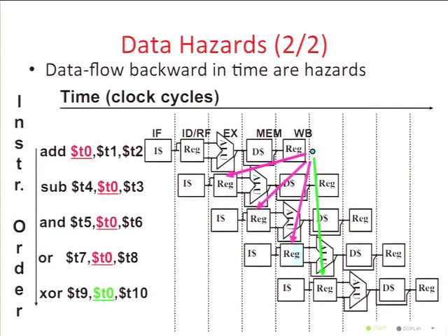So it turns out, where do we know we're adding, we're going to skip that step. So it turns out that right here, we actually know the result of the add, okay? So for the cost of one wire, I could probably solve my problem, okay, or maybe multiple wires. Okay, so this is called forwarding. So I can actually change my wiring in order to solve these kinds of hazards. You got to get the control to work properly then, but you can do it.